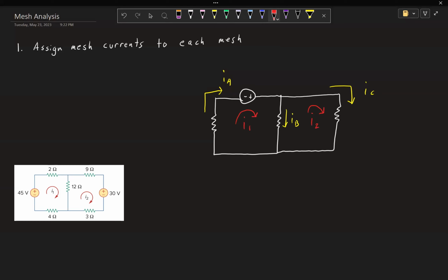Now, when we go on the outside of this loop, following this path right here, we can see that I1 is equal to IA. They are in fact the same. However, when we are right here in the middle of the path, IB is not equal to I1. Even though I1 is going down next to IB, you have to look over here. There's this I1 going down and there's this I2 going up. So here you could define IB in terms of the other two by saying IB is equal to I1 going in the same direction minus I2 going in the opposite direction.